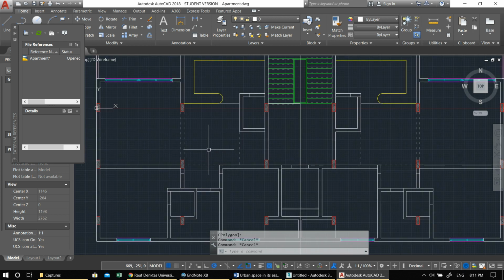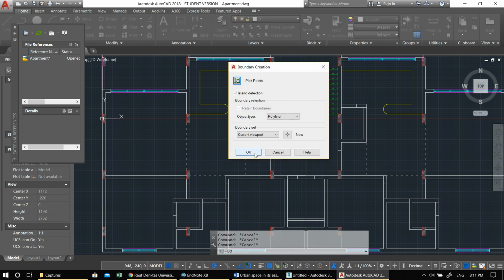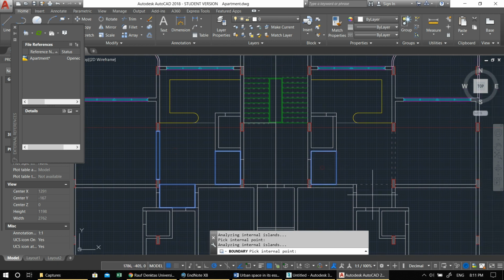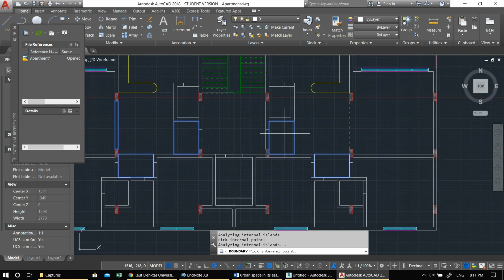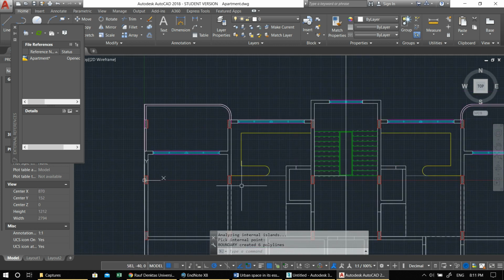Now if you want to have more precautions, like you want to have a suspended ceiling happen on this kind of stuff, if later you want to do interior, I would advise you to use the command boundary, because it's much easier to do in AutoCAD, and give these their own boundary if you're planning to extrude them, bring them up and down, or anywhere that you have a difference in level. I would advise you to draw a boundary around it, but be careful not to mistake them with wall when you go into the program itself.